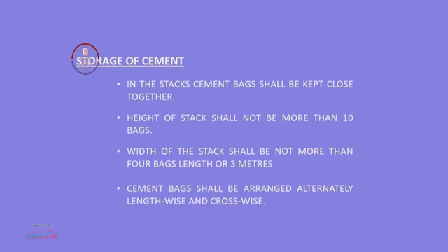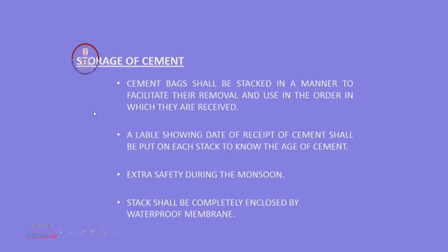The width of the stack also we have to see: more than 4 bags should not be there in one stack. And lengthwise, it should not be more than 3 meters. And if you go for higher stacking, up to 10, more than 10 is not allowed. If you go for stacking up to 10, it should be arranged alternately, lengthwise and crosswise, to avoid toppling and to avoid accidents.